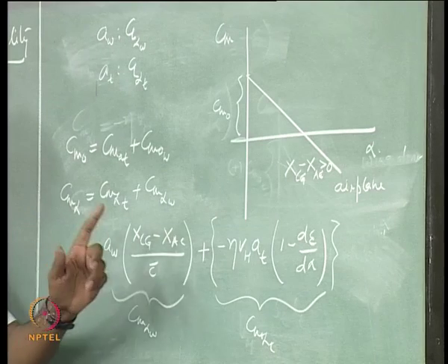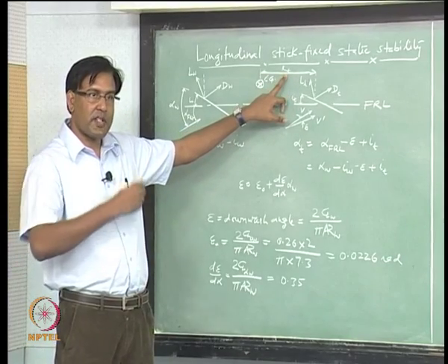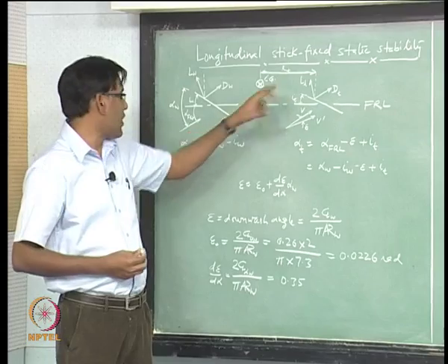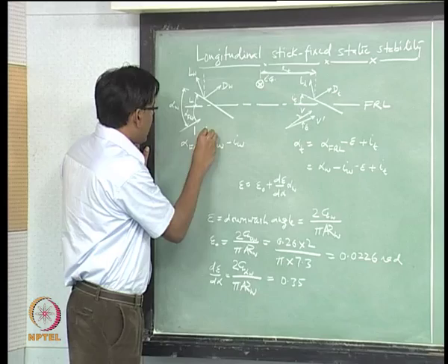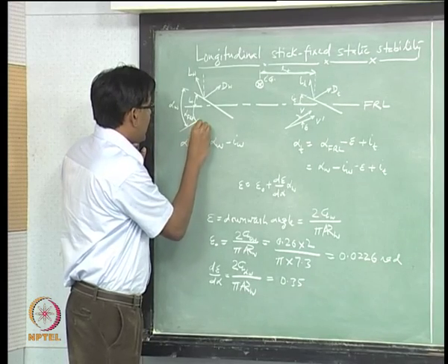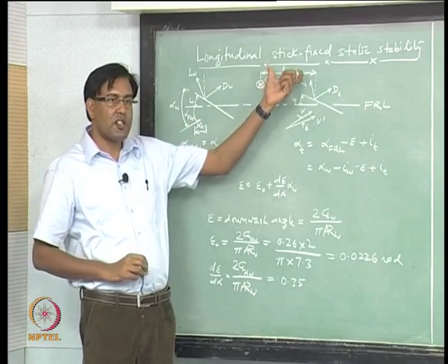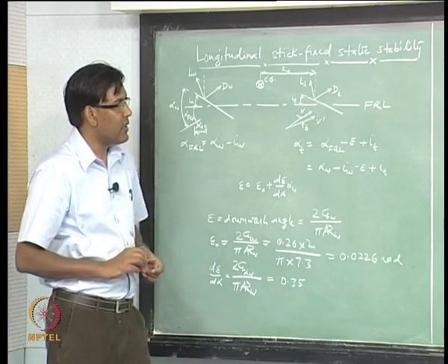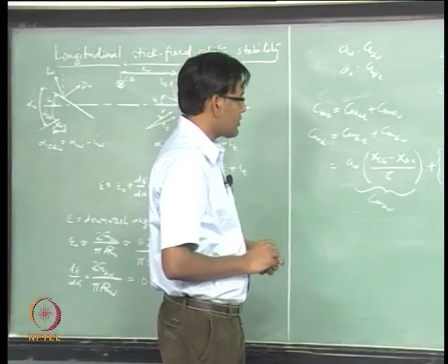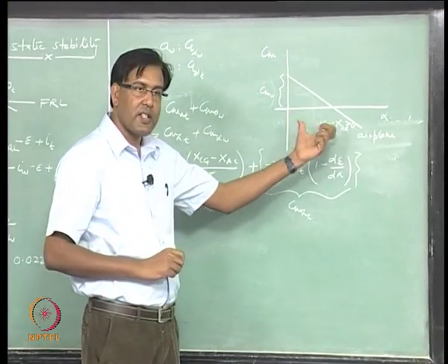Cg is of course going to have an effect also on the tail arm length, right. This Lt is also going to change if you start changing the Cg. Not only this distance x Cg minus x AC, but this Lt is also going to change because of the Cg travel. Okay. So, let us look at this curve. What will happen when the Cg travels?